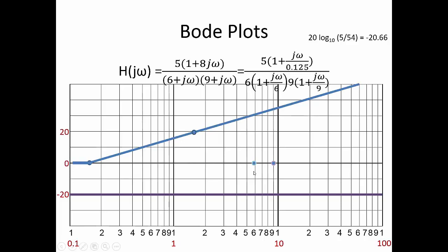For the next one, we're over here at 6. It's flat till we get there. Go forward 1 decade. It's in the denominator, go down 20 dB. Put another dot, play connect the dots.